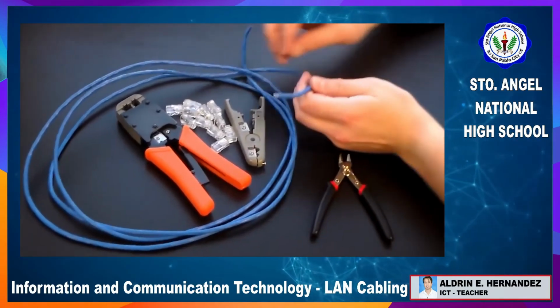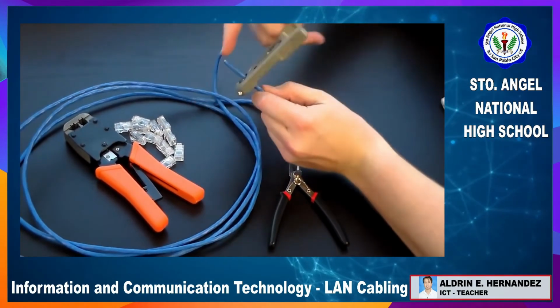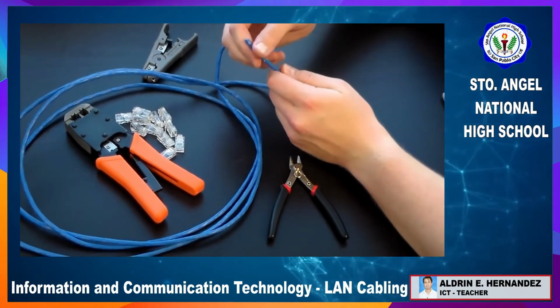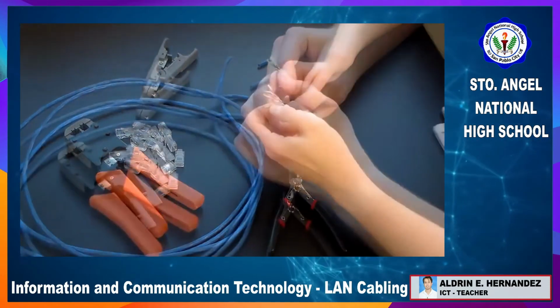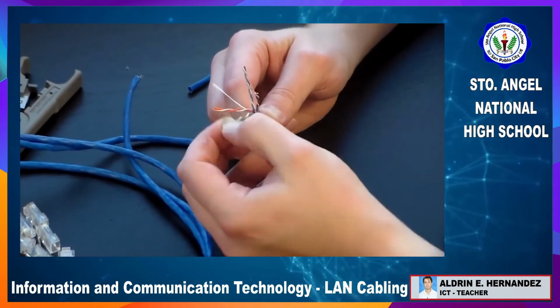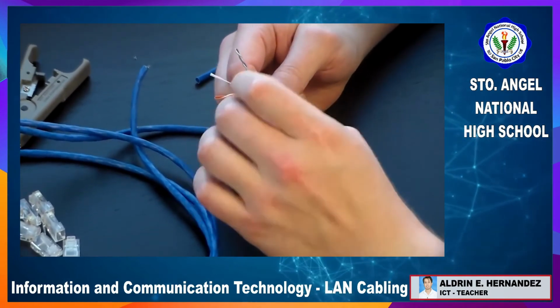Hey guys, alright, today we're going to crimp an Ethernet cable. So first, what you want to do is remove the sheathing on the wire using the handy dandy wire stripper. Pull that sheathing off. It's going to expose the twisted pairs. It's going to take a few minutes to separate each pair and then untwist them and get all the wires nice and organized.